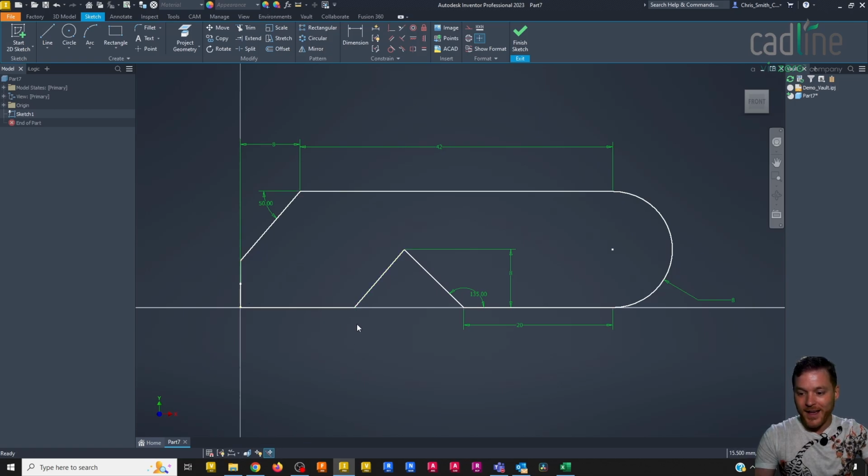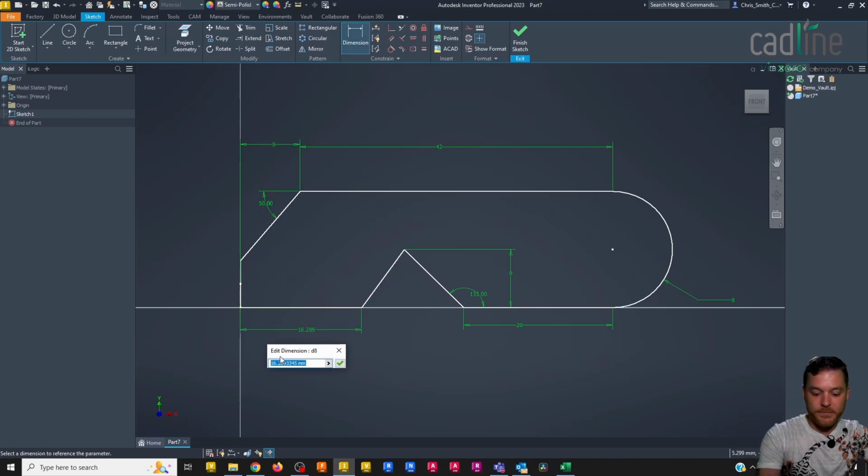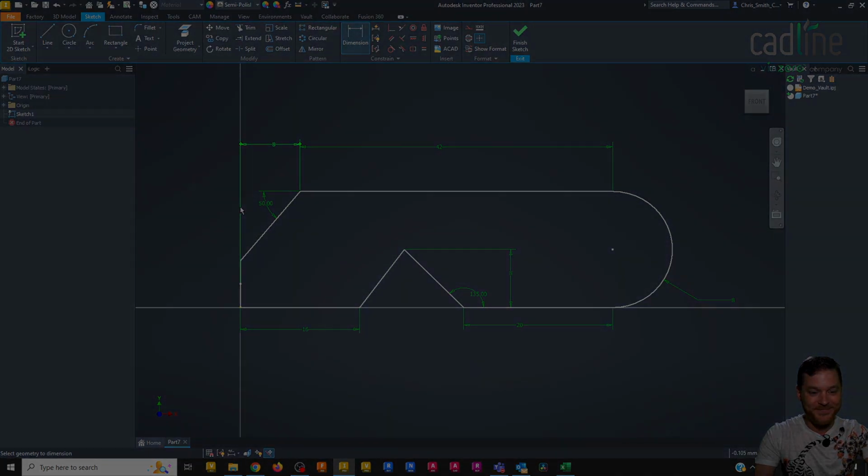let's just hide those. Selecting relax mode actually lets me move these around. So we can see now that as I pull this point around, you can see that there's constraints in magenta boxes. It's highlighted because these are the constraints that have relaxed. So once again, I'm just going to change this, and now I can add in my dimension, and it's no longer limited by the constraints. So there we go, that's a nice short little video, just some tips there in the